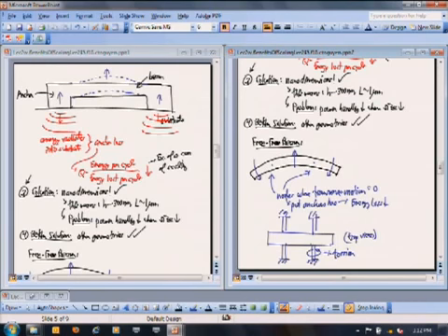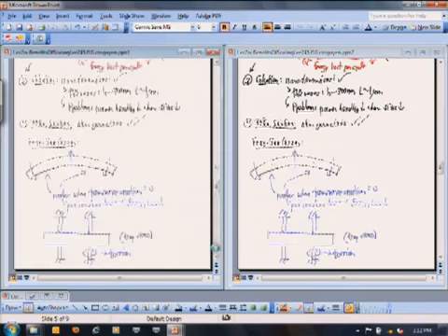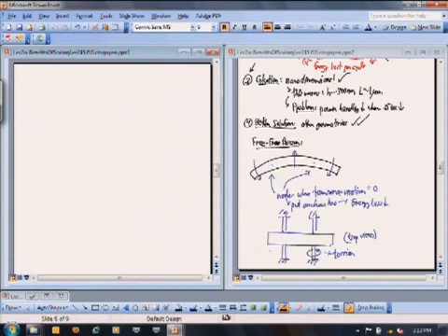I mean, think of this. This is the same problem as loss in an inductor, right? So for a transistor designer, you have an inductor. Okay? The inductor suffers quite a bit, not only from losses in its turns, but also from losses because there's magnetic coupling to the substrate. And the magnetic coupling to the substrate creates eddy currents in the substrate. Those eddy currents have to go through resistance, and so there's loss.